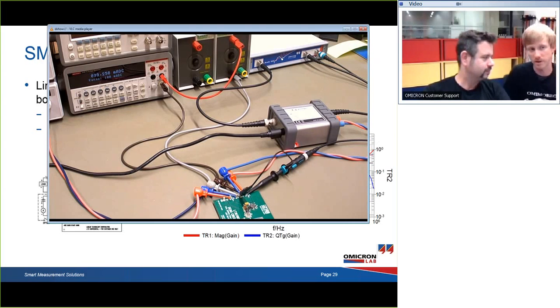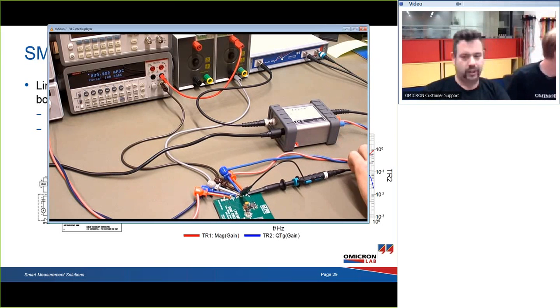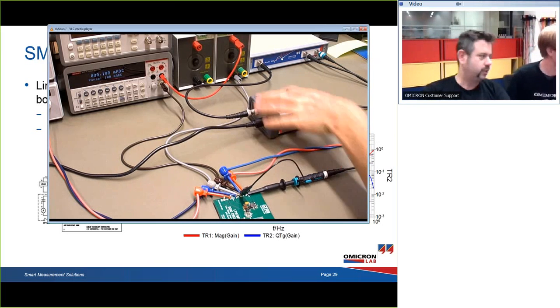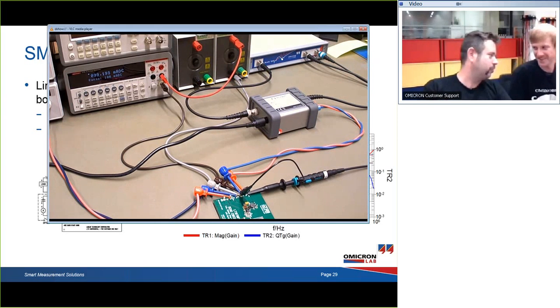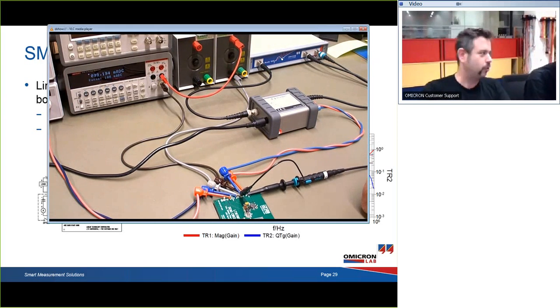Otherwise, it would have a phase margin of more than 90 degrees, and we wouldn't see any peaking in the output impedance. And you also gave it a high supply voltage of 13 volts, to make sure that it has enough headroom, so it has really nothing to do. And if a regulator has nothing to do, it gets bored, and then it results in a bad phase margin, something like that, right?